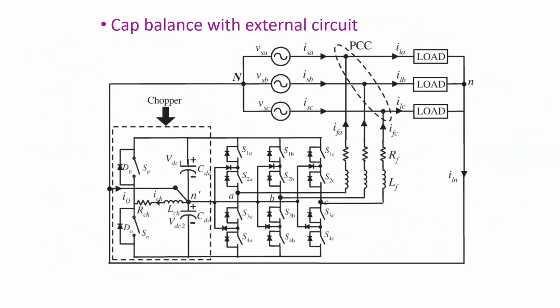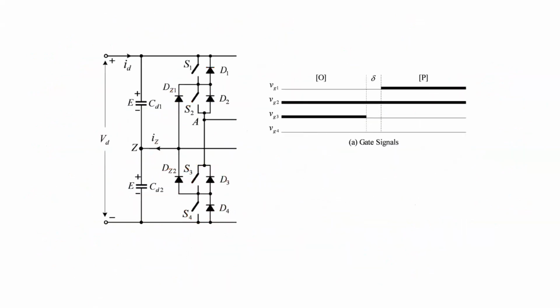Whereas here, when we come to this, what is the device blocking voltage here? This is VDC, and this is VDC, and this is VDC. This one is also VDC, right? In 3 level, this is VDC. So how much is it? It is 6 VDC per phase. Agree? So the device overall blocking voltage is 6 VDC per phase. All right.